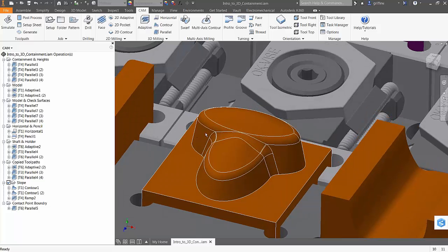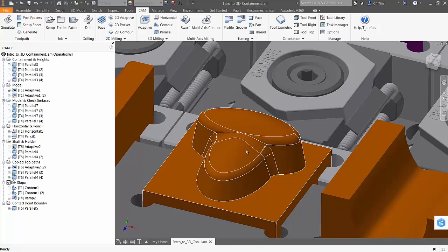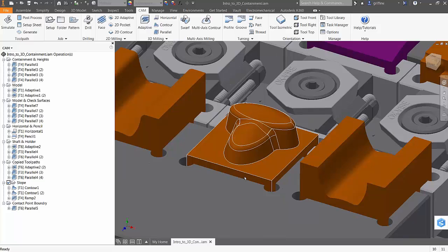So as you walk down, you think you would have less code, but it all depends on the number of points, because now as it steps down, if you're doing linear, depending on how your tolerance is set up, you would get a lot more code because it's constantly moving. You're constantly getting points in the X, Y, and Z. But that's the way I think of it. That's really my understanding of how it works. I could be wrong about why you're getting more code.